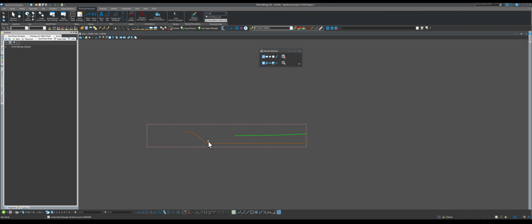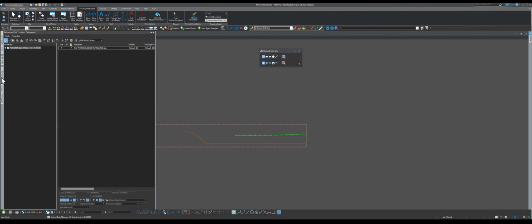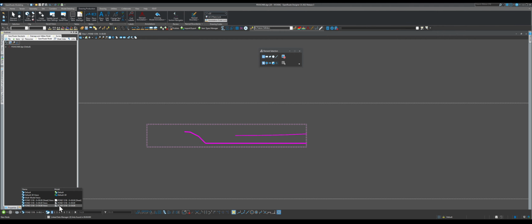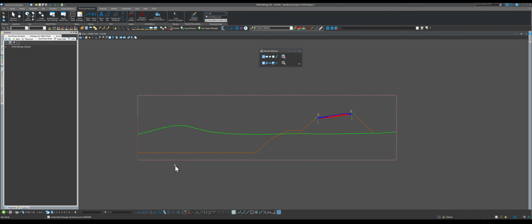As you see, this is a section, a named boundary straight up from where? From the model, right? This is live from the model. And if I even go to the other one, live from the model. So when the roadway changes their stuff later, it will update this. So what we can do is we can just pick one of these views, one of these sections, the top one or the bottom one, and then bring the other one here.